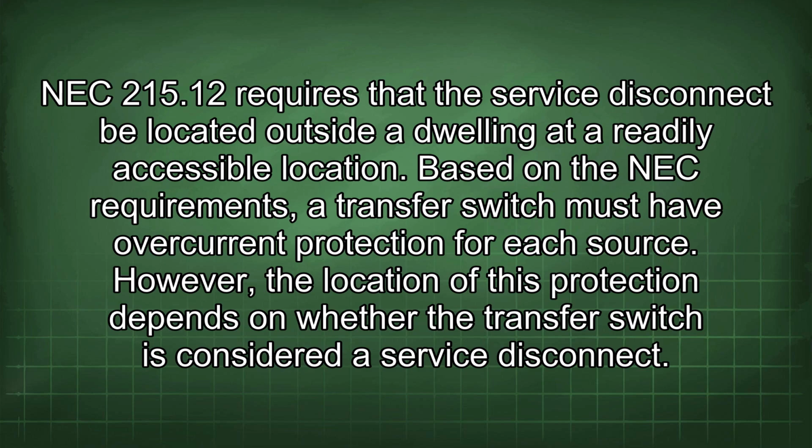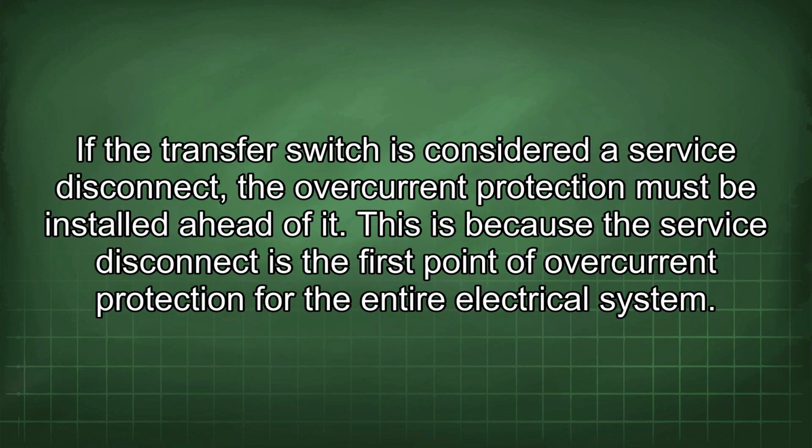Based on the NEC requirements, a transfer switch must have overcurrent protection for each source. However, the location of this protection depends on whether the transfer switch is considered a service disconnect. If the transfer switch is considered a service disconnect, the overcurrent protection must be installed ahead of it. This is because a service disconnect is the first point of overcurrent protection for the entire electrical system.